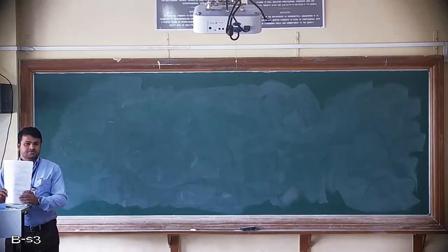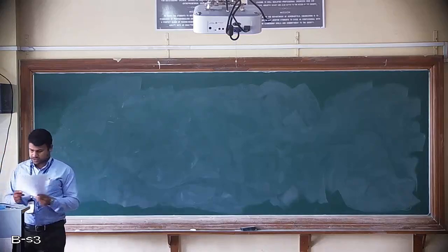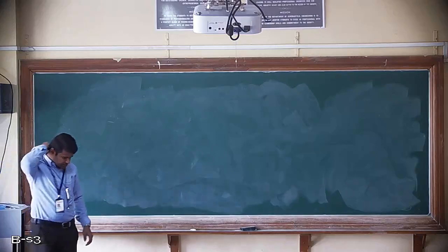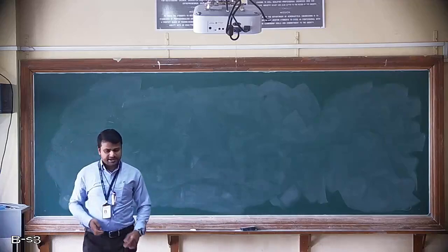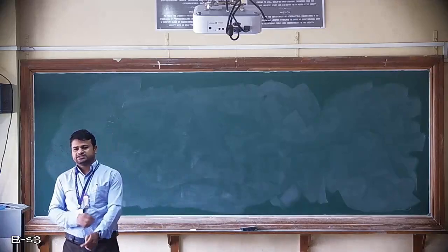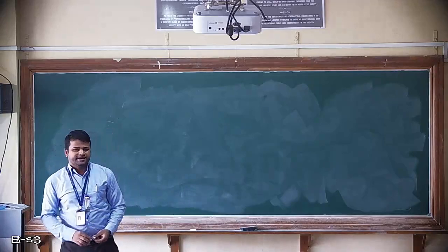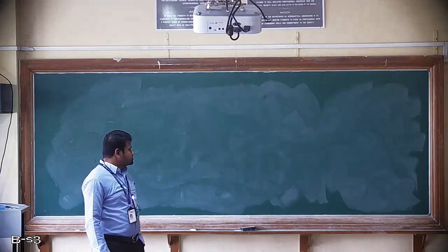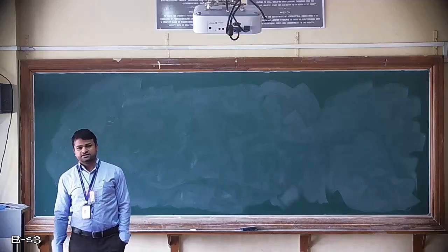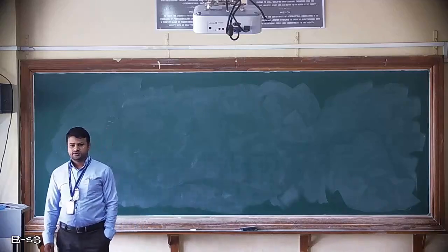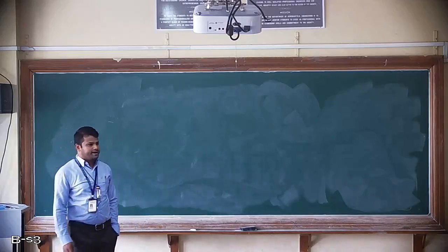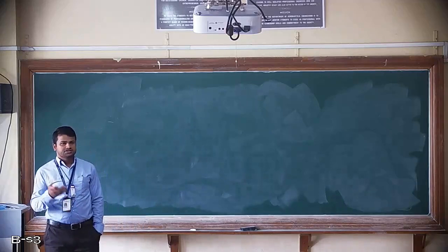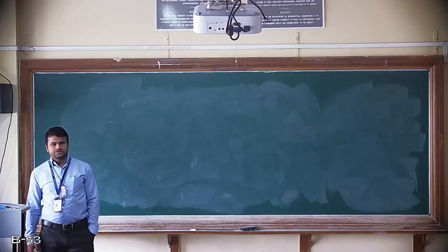And the stability and control part we discussed, where we saw different types of stabilities, whether longitudinal stability or dynamic stability. Also we saw the subcategories: positive, negative and neutral, and statically stable but dynamically unstable, how the situation will be. That also we discussed.